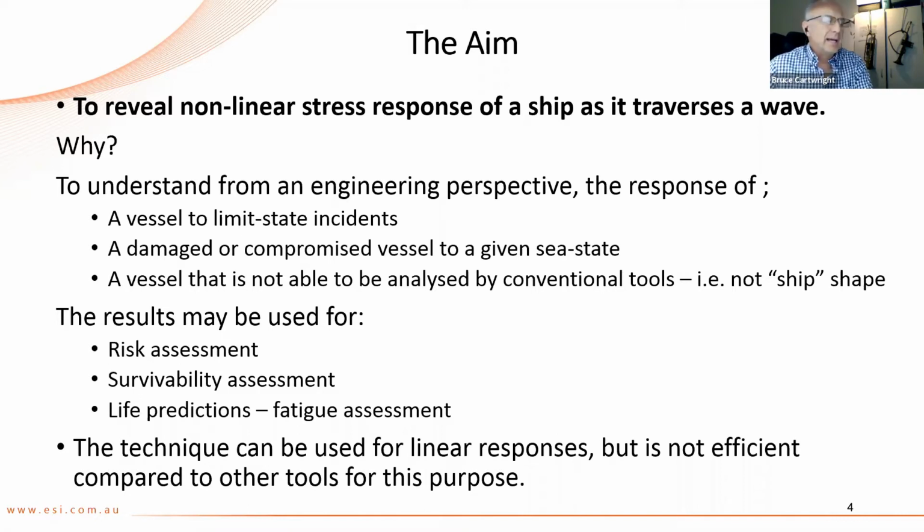I guess that's this last comment here. The technique can be used for linear responses, but it's not efficient compared to other tools which naval architects are familiar with for this purpose. So we might be able to reproduce an RAO of a boat, but it'll take us an awful lot more CPU time and effort than to push the button on your Maestro or other software.